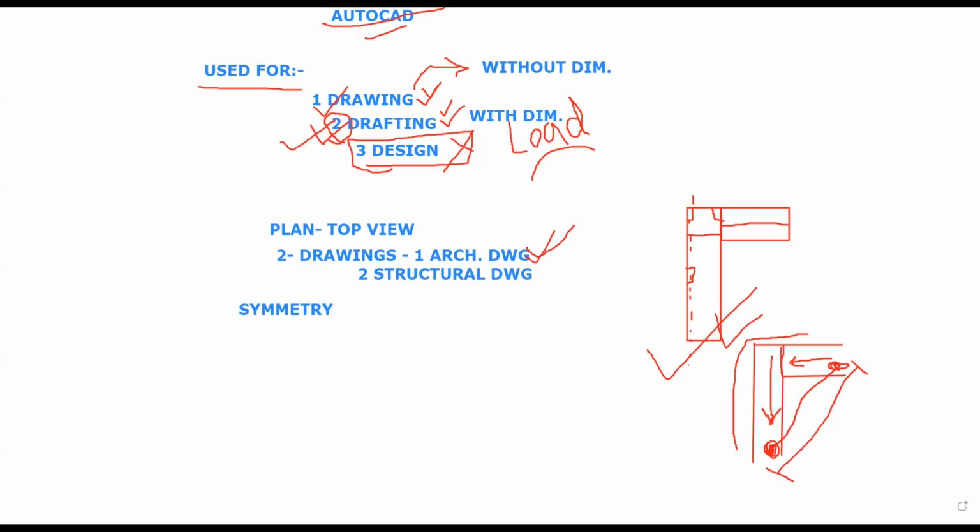So the next part of it is location of the beams. Just once again, just repeat it. Two columns spacing should be between 10 feet to 16 feet. This is your first point.